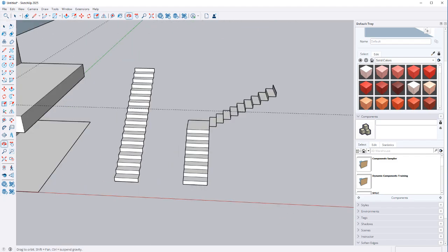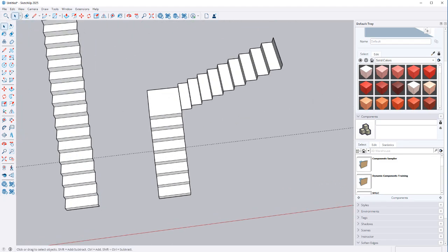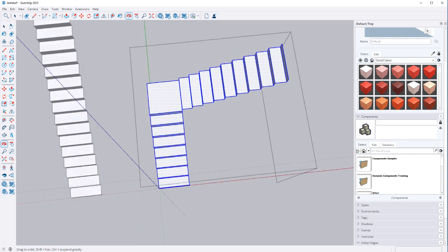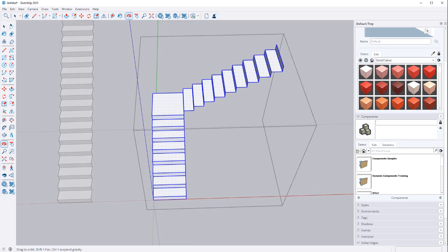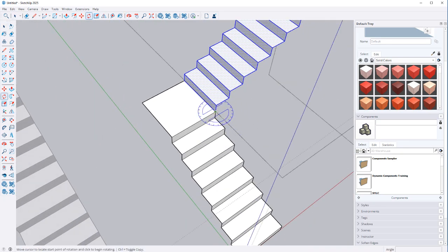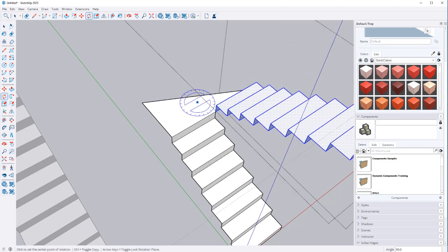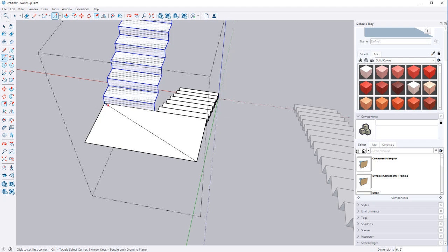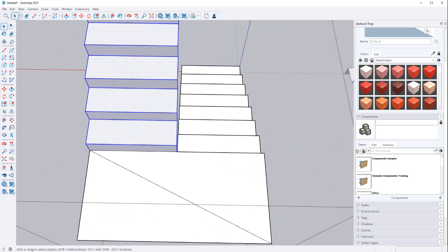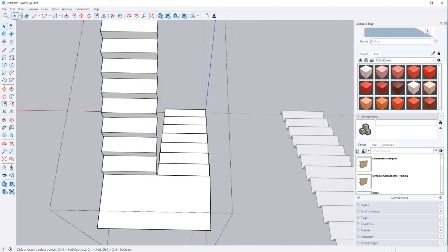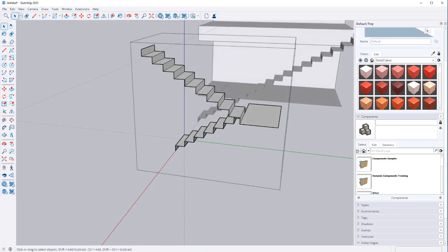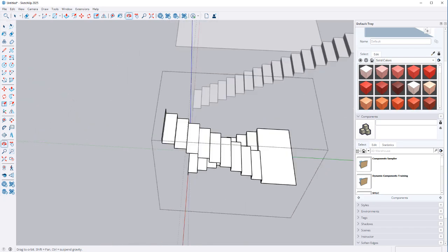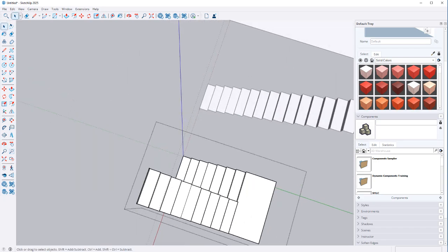So that gets kind of, if you need to put a corner in, if you need to go something even more than a corner, again, you kind of start getting off into very individualized solutions at that point, but I can still take this and loop this around. Now, you would want to add a little bit more space in here because the thing I haven't quite mentioned yet is railings, and you'd want to have a railing between these two flights.